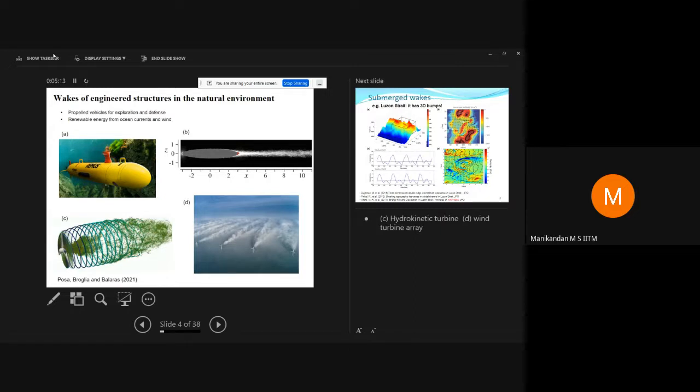So here stratification matters because eventually, although the speed may be large and the relative effect of buoyancy may be low, the time scale of the flow becomes small enough that it becomes comparable to what we call the buoyancy time scale. And the buoyancy time scale basically increases as the stratification does, dρ/dz. We're talking about a vertical gradient.